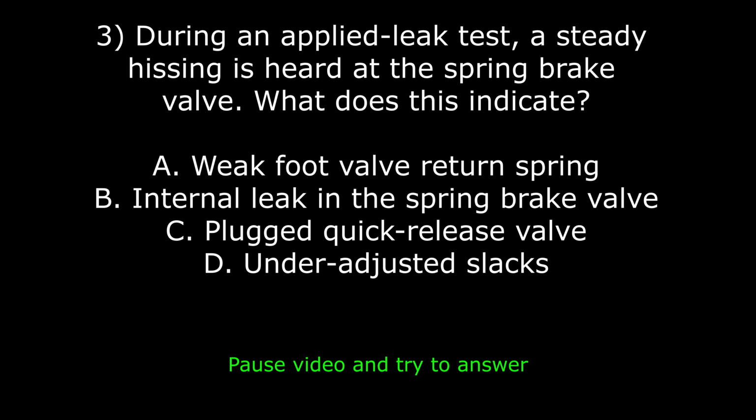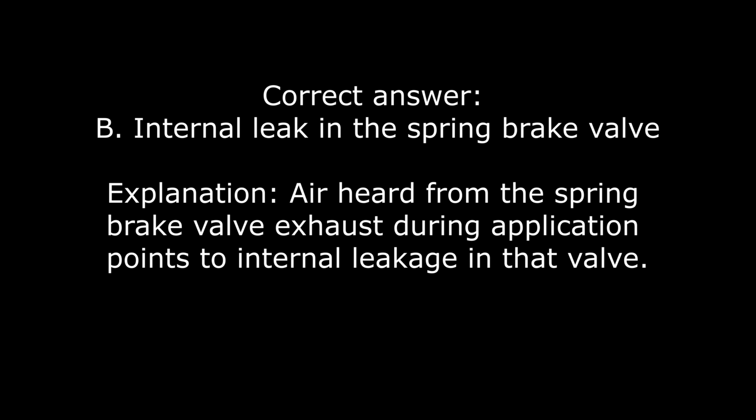3. During an applied leak test, a steady hissing is heard at the spring brake valve. What does this indicate? A. Weak foot valve return spring. B. Internal leak in the spring brake valve. C. Plugged quick-release valve. D. Under-adjusted slacks. Correct answer, B. Internal leak in the spring brake valve. Explanation: air heard from the spring brake valve exhaust during application points to internal leakage in that valve.